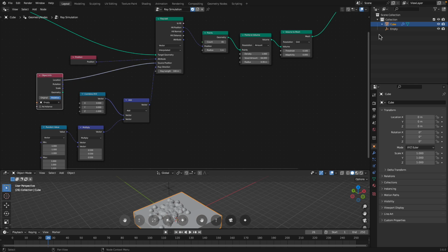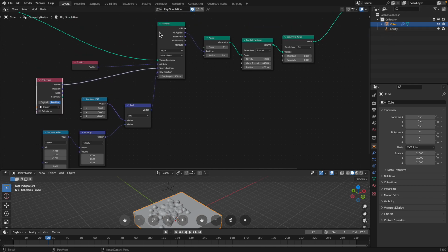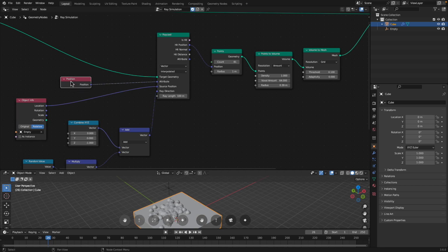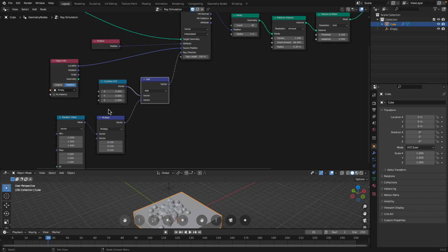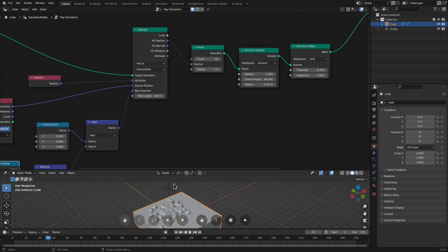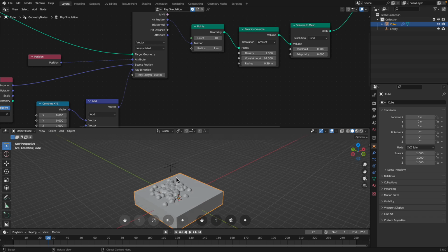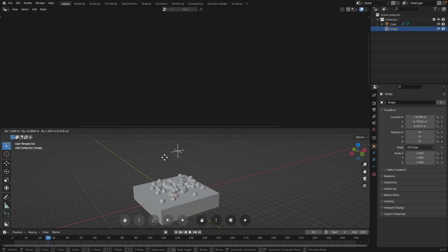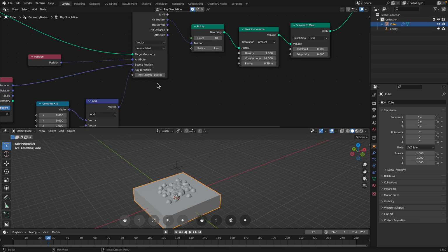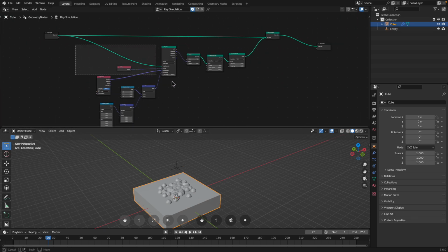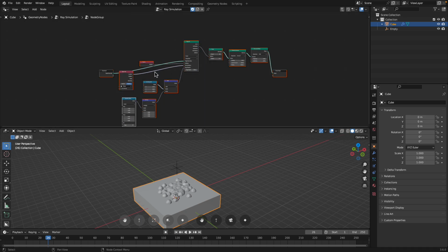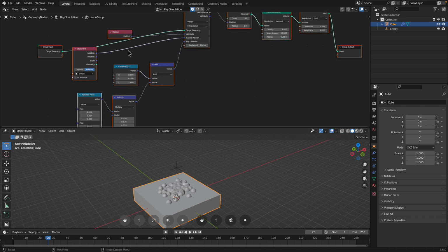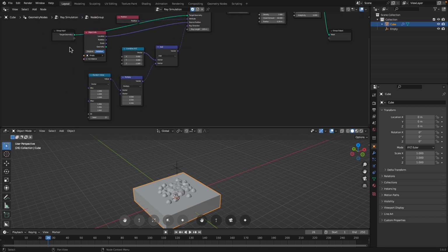So again, it's an empty position, goes into the Raycast, and we are looking at the position, and then we use the ray directions that have been scrambled using a random value, so it's pointing down. So this already works. Okay, what's happening next, I just select all of this and then Control G. So I'm grouping those nodes, and I like to pipe in the seed value.